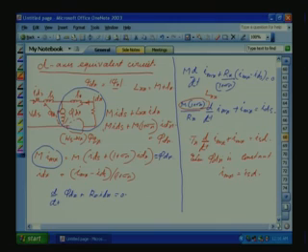Then why this first order equation happens? This is valid during the field weakening region when we slowly reduce the flux. So, when you slowly reduce the flux, the variation of ISD and the flux is proportional to the first order thing. Otherwise, not in the flux weakening region, that is in the constant torque region, IMR is equal to ISD, that is below the base speed IMR is equal to ISD. So, this condition we got.